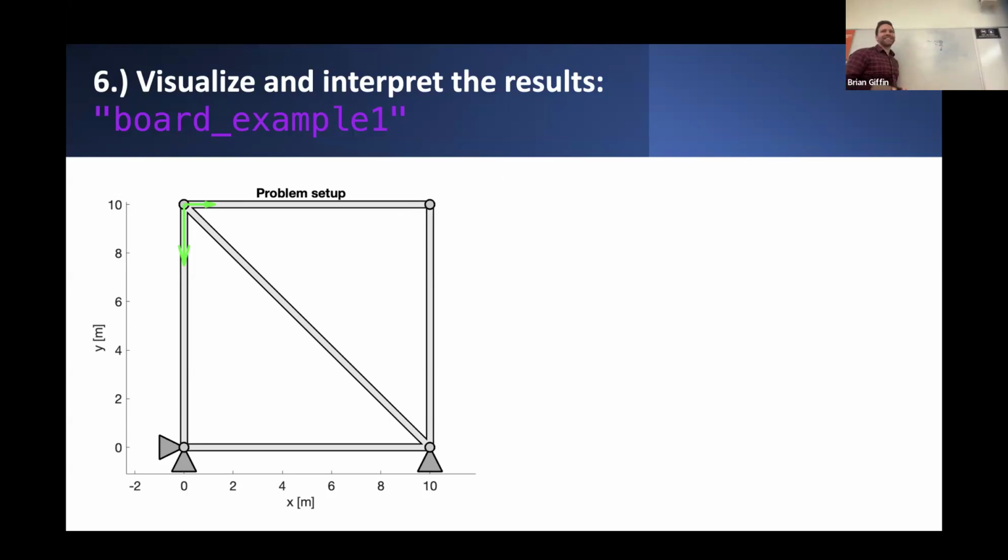They're not coming in at the same angle. If I take the sum of forces in the x direction and the sum of forces in the y direction at this joint, in the y direction there's only this one force. There are no other external forces that could balance with it. So the only way for this joint to be in equilibrium is for this force to be zero. And you could make the same argument about that x-directed force. So indeed, we find that those top two members are going to be zero force members.